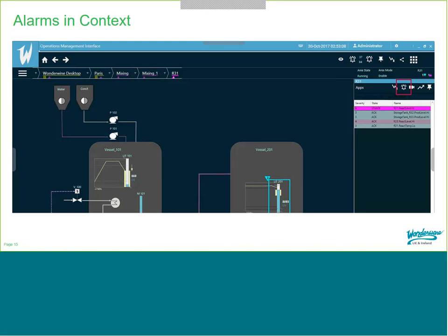Whereas with this, on the right-hand side you can see a faceplate for the overview window in the middle. When we select the alarm element associated with our faceplate, it will automatically only display the alarms that are relevant to the area you've got open, without the need for scripting. Again, that reduces engineering and the reliance on making sure you've done things correctly and replicated it throughout the entire system. We don't have to worry about that kind of thing anymore.